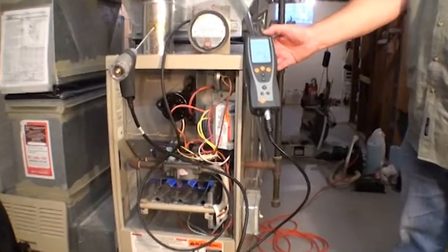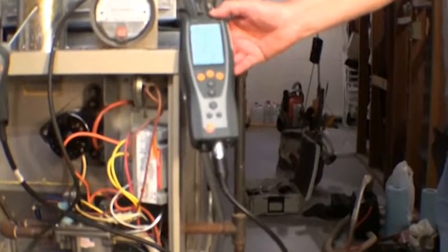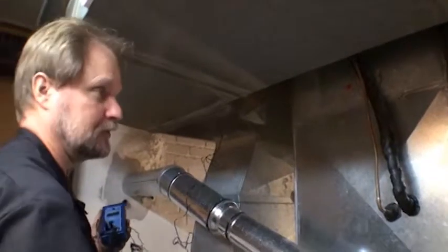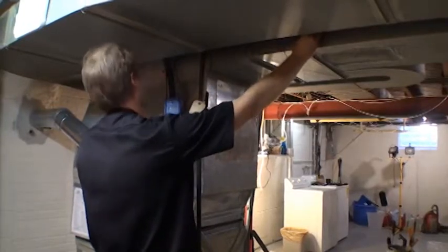Perform a combustion gas analysis of the furnace flue gases and ensure they are within the acceptable range provided by Community Action. Write the date and the combustion analysis test results directly on the return drop in permanent marker. If you are not able to get all the levels within the specified ranges, call Community Action. Perform a heat rise test to ensure the furnace is operating within the range indicated on the furnace data plate.